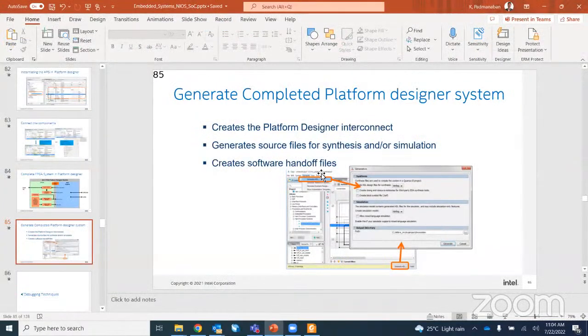Right. So what is the logic here? What we have done is we have taken an SoC design, which is available in the GHRD. And we have gone through the Platform Designer, integrated with the Quartus Prime design software, and compiled the design. And we have seen what resources are taken on the HPS section as well as on the FPGA section. And we have noted down the FSM. And also we have seen what is happening in the timing analysis and whether the slacks are positive.